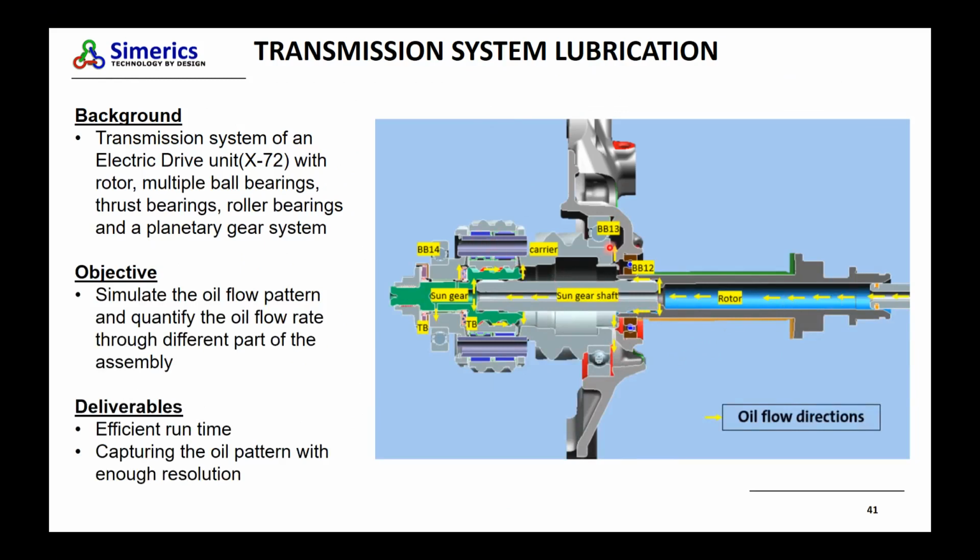Actually, this system has 3 ball bearings, 1 thrust bearing. There's a thrust bearing here. So that is 4. And then we have 2 sets of needle bearing on each of the planet gears, and there are 4 planet gears. So that's a total of 8 needle bearings. So 8 plus 4 is 12 sets of bearings in total. And then we have the gear mesh as well, which is 4 planet gears, 1 sun gear, 5 gears, and then a ring gear, totally 6 gears.